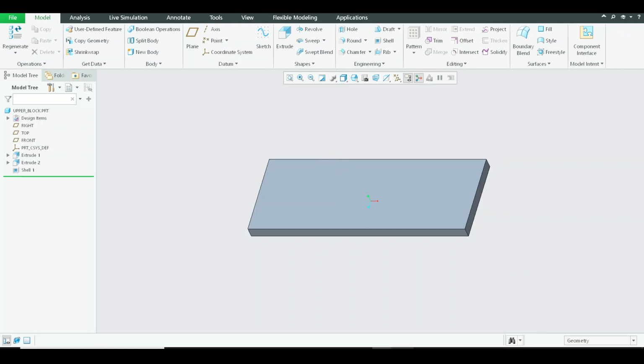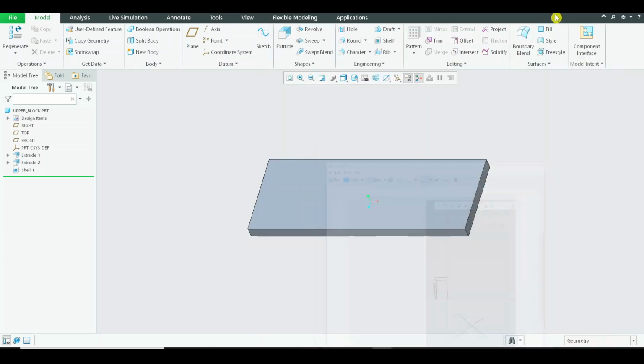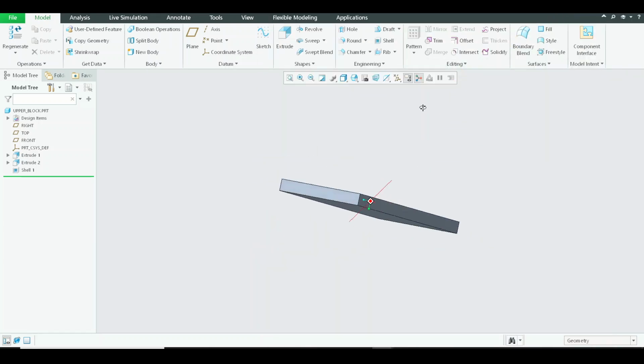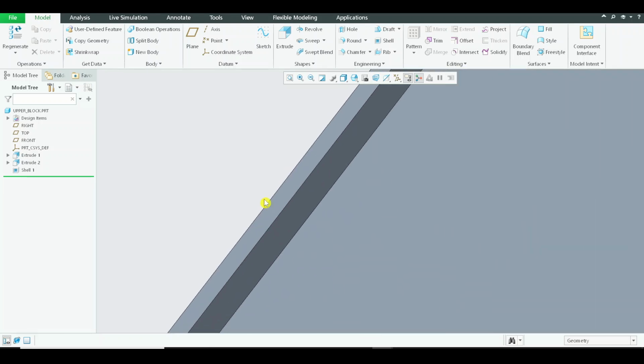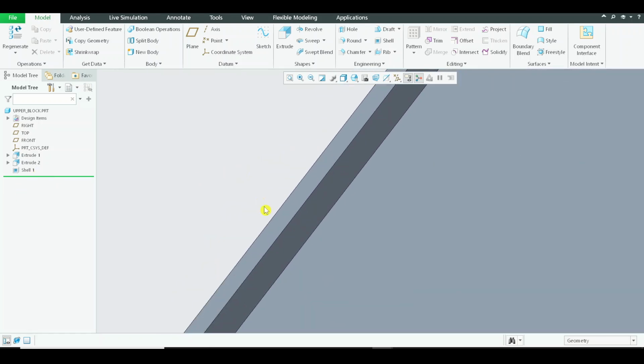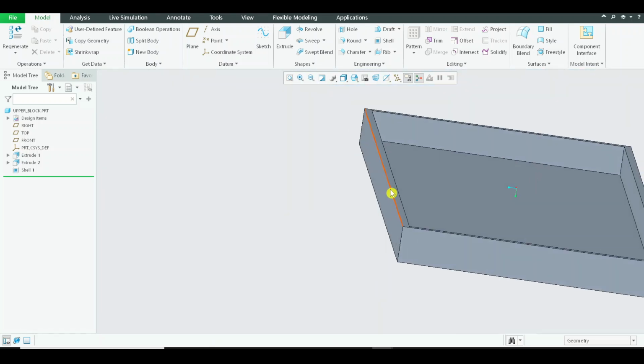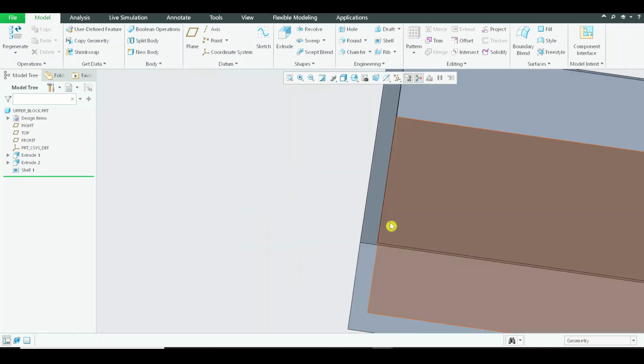Alright, as discussed in the previous video, we will be creating these additional protrusions or extrusions around the perimeter of the object, and we will see that they help us join the two parts together. Now, one thing to note: the minimum thickness of the material I have created is 2 mm, but if we add a protrusion on the top, that will be half the size of the thickness, so that will become 1 mm, right?